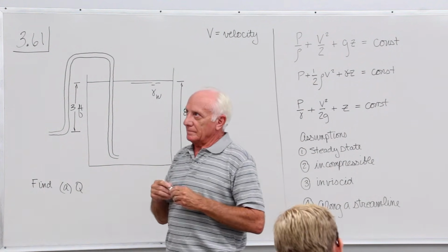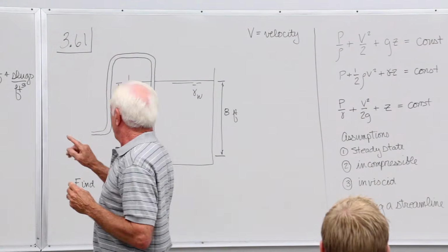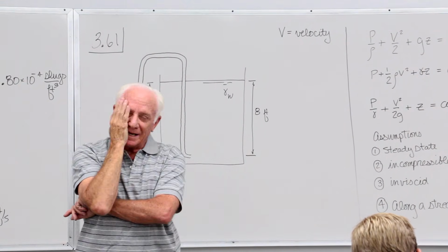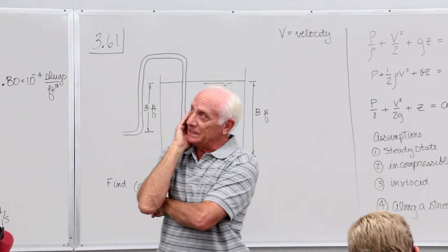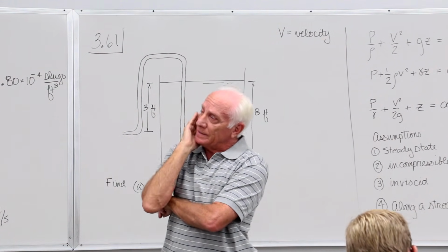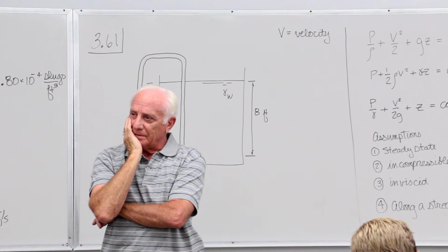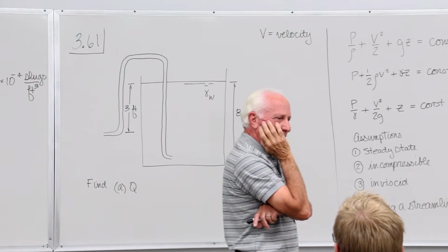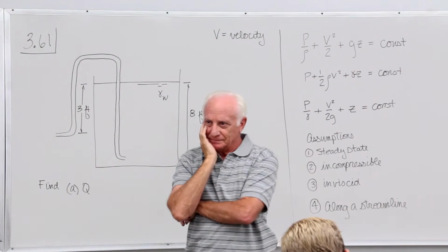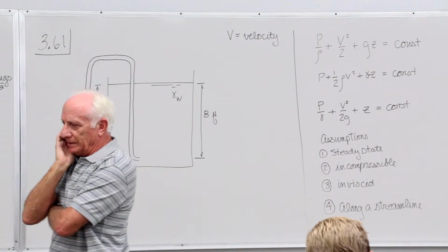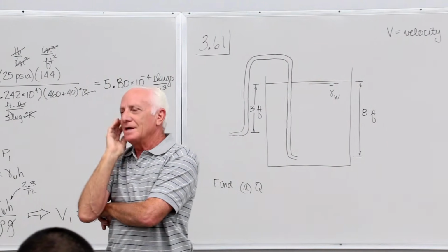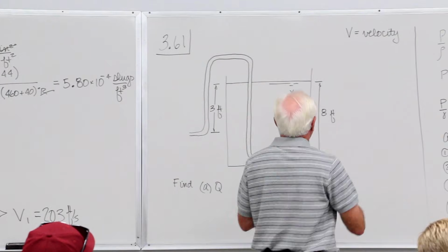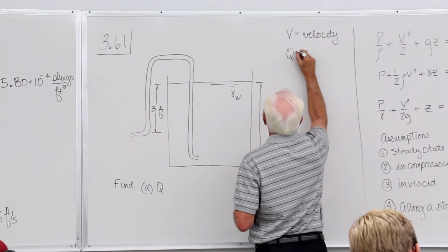Now comes a flow rate. Okay, this HVAC duct in here. You think those guys, when they analyze those HVAC ducts, say the flow rate in there is 50 gallons of air per minute? Are you kidding me? No, you know the language they speak? CFM. Or maybe liters per second. That's called volumetric flow rate. So number 2, Q, volumetric flow rate.